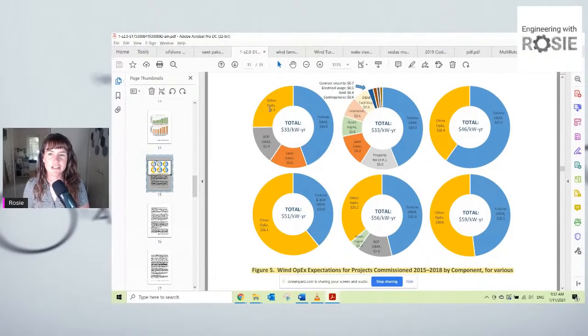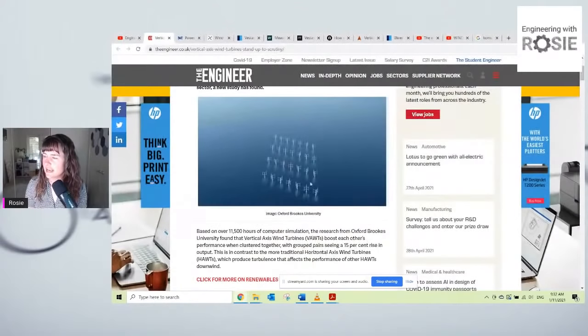That makes it difficult. I just wanted to point out that just because you can pack more vertical axis wind turbines into a site, that only matters if your land is constrained. If you need to clear your land and put an access road into every single one of a bunch of small turbines, that's probably going to be more expensive than if you just have a few big ones with one road per turbine. I think offshore it will probably be different, but I don't actually know precisely how they lease the water when they put in an offshore wind farm.